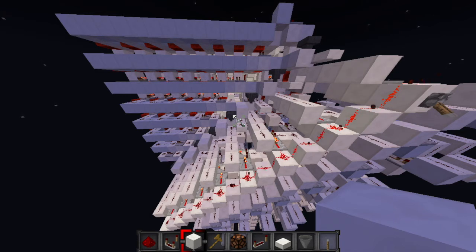One interesting thing about the rotate function is that technically a rotate left once function is the same as a rotate right 7 times function, because if you think about it, the bit configuration stays exactly the same. It's just which position each bit moves to. So that means we don't need two separate rotate left and rotate right functions. We can just have one rotate left function that is all-encompassing.